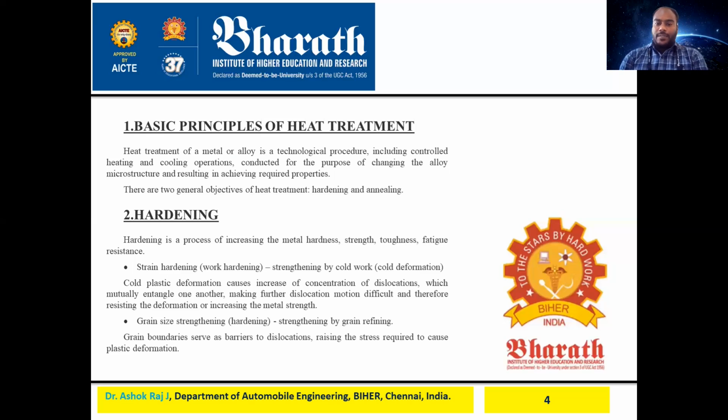Cold plastic deformation increases the concentration of dislocations, which mutually entangle one another, making further dislocation motion difficult, and therefore resisting the deformation and increasing the metal strength.